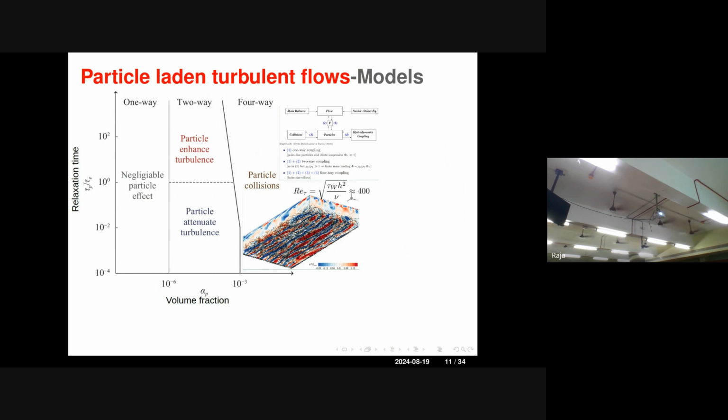And usually, based on the volume fractions, people try to look at whether particles can influence the flow. Particles can influence the flow, but it is more like two-way coupling. Maybe particles rotate and also influence the flow by creating rotary structures, a four-way kind of coupling. This is the standard point-particle approach that people use. Otherwise, for a particle like a solid sphere, one has to resolve that entire thing by an immersed boundary method, or perhaps write complete structural information and resolve the stresses acting on the particle and how these fluctuations really interact. That's another way to do it.